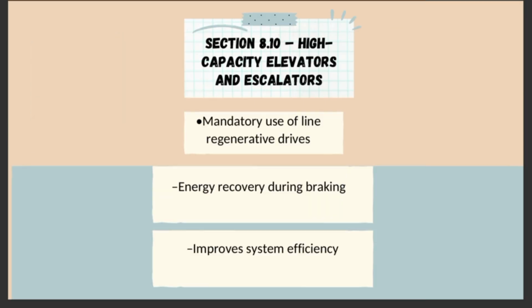Section 8.10 High Capacity Elevators and Escalators. For high capacity elevator and escalator systems, the use of line regenerative drives is required. These drives allow energy generated during braking to be recovered and reused, improving overall energy efficiency and reducing electrical consumption.